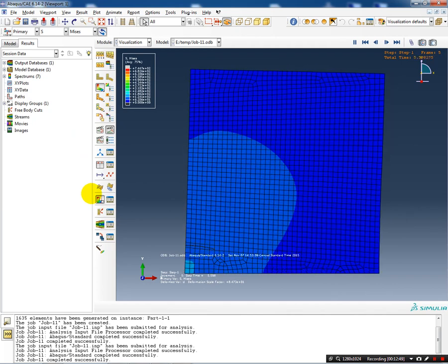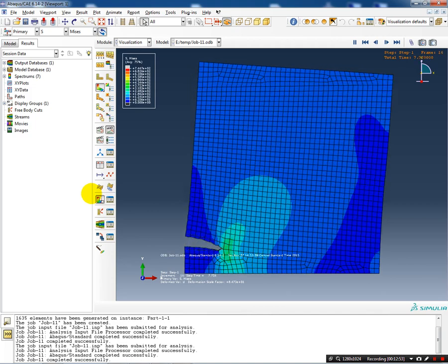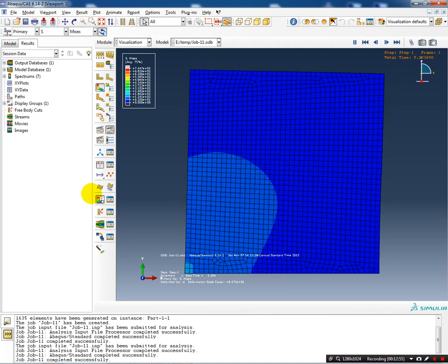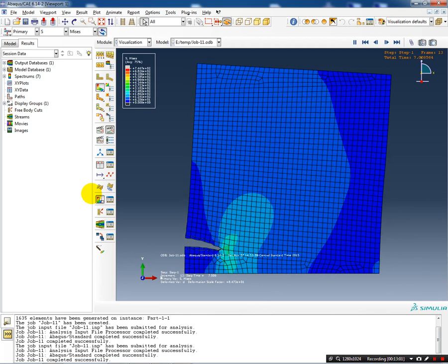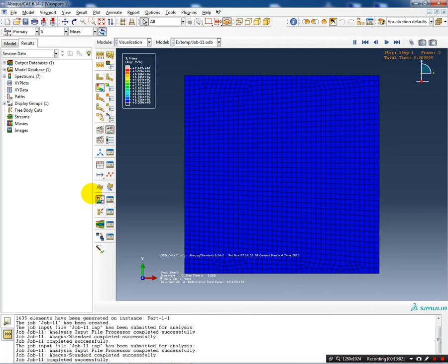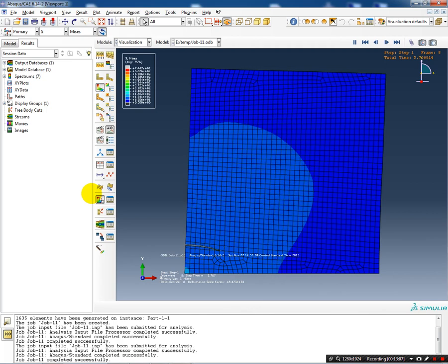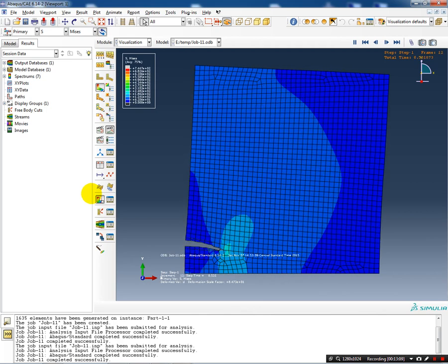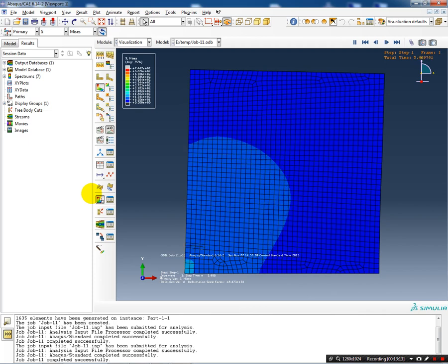It actually forms in the interior just a little bit, propagates out to the left edge, and then it starts propagating, and it hits the boundary, kind of arcs, and it hits the boundary, and that's where we start to get to our mode 1 opening and the typical stress field pattern, that kidney bean shape, if you will, that we see from our prior stress analyses.